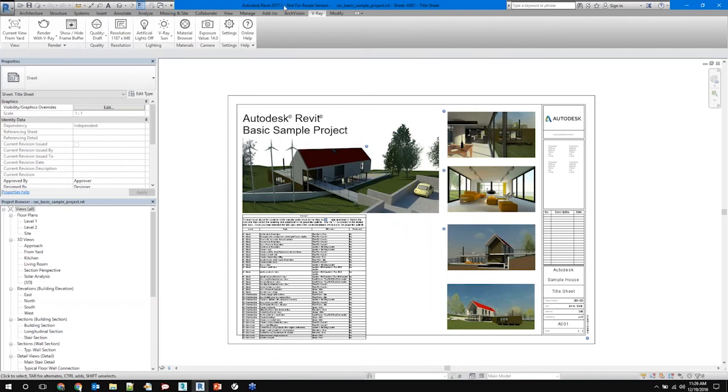I'm happy to note that in 2017.1, when you are inside of a camera view, you can actually send a rendering now. That's something that we couldn't do before, but Autodesk has listened and opened up part of the API to us that they weren't able to before. So we're going to have a patch out soon that's going to take advantage of that in 2017.1. But if you have the existing release version of V-Ray for Revit, you can now send renderings directly from 3D views. For those who are in older versions of Revit, 2016 and 2015 for instance, you can still select your individual cameras directly from the project browser here.